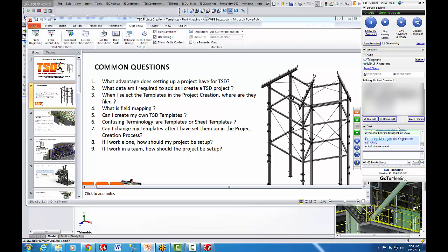Our file naming convention is set up so that when it comes to DST, VC, and C, there's a limit to the number of letters you can use for your marking number. It can be numbers also, or just letters. It can be numbers, but you're restricted then. So you've got 99 numbers, 0 to 9 and 0 to 9, whereas if you use letters, it's 26 by 26. So on really large projects, it's best to use numbers.